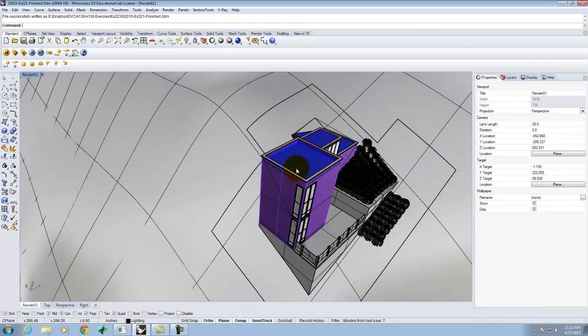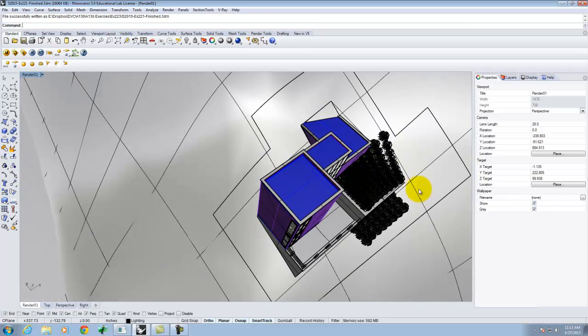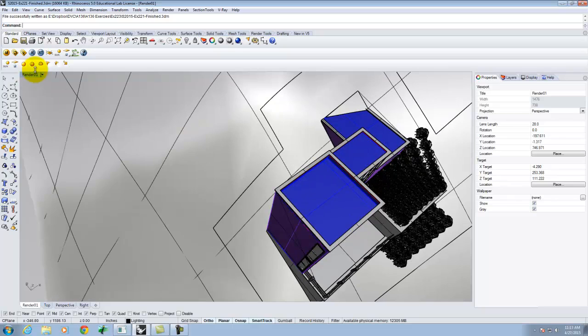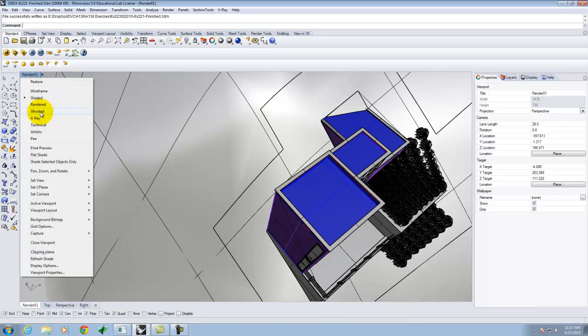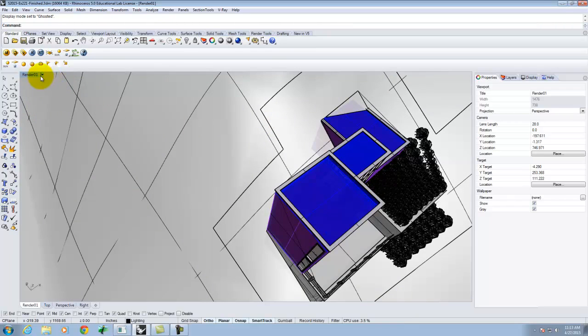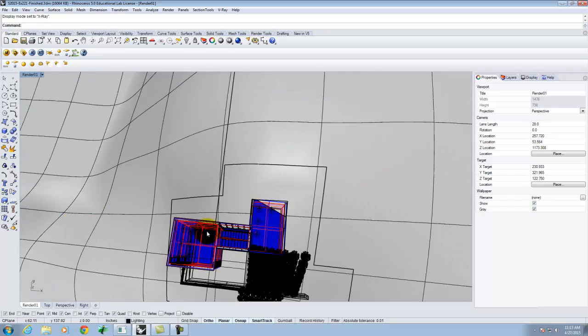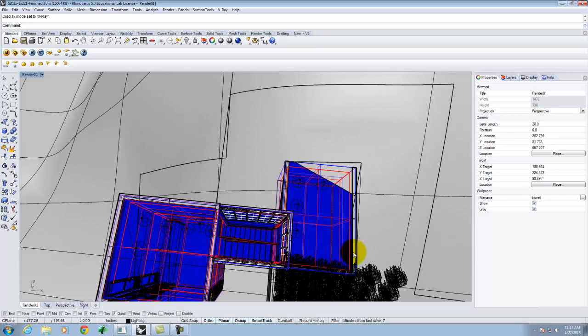So as I look at this building and I think about cutting a section, the section that I want to cut is going to end up going through the stairs. So if I show this in ghosted mode for a little bit, actually let's go into X-ray mode and you might be able to see a little bit more. I want the section to cut through one of the flights of stairs, and I want to be looking at the building so that I can see these 2 rooms.